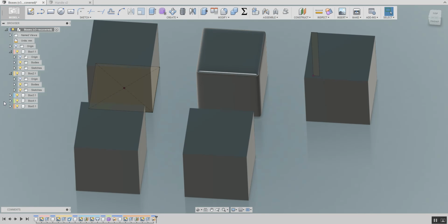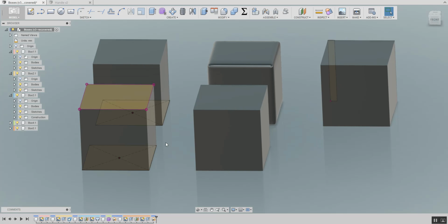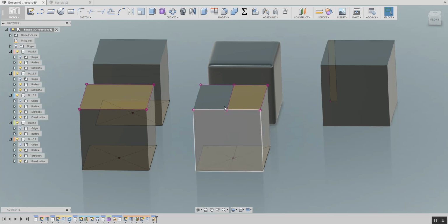And let's go to the third one. It's this one. I've used 2 sketches and created a loft. The fourth one is this one. It has no sketch because I used free-form modeling to create it. And the fifth one is this one. Again, it's 2 sketches. One I've extruded this way and the other one the other way. And there are many other ways to make the box.